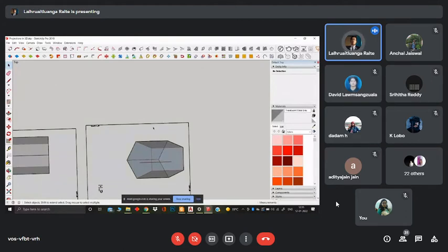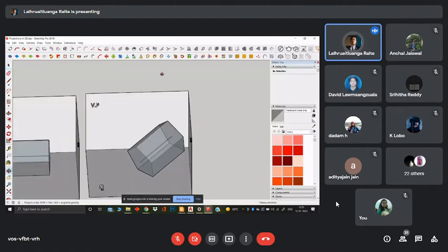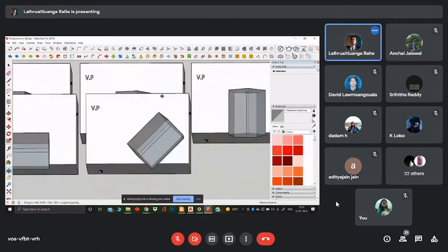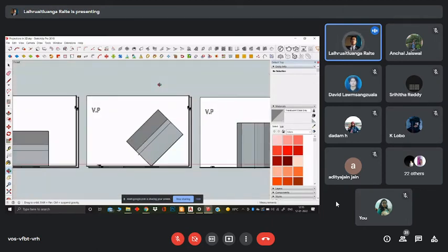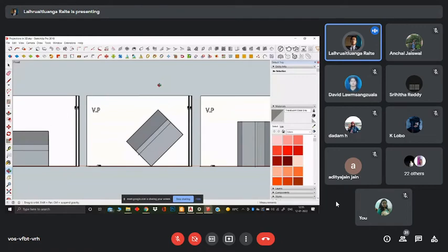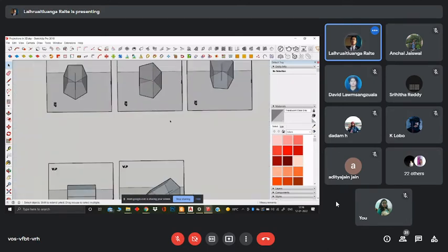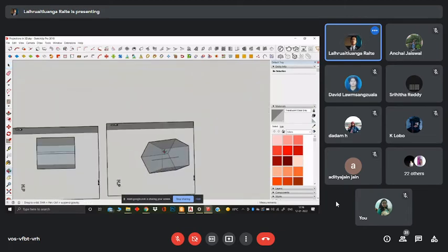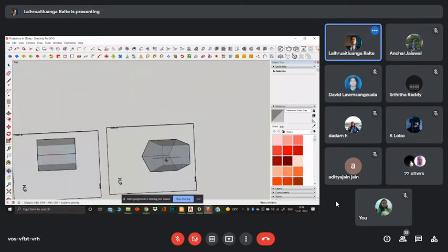This is the vertical plane, or the XY line, and our axis is still parallel to it. So now we have our conditions met: the edge of the base is touching the horizontal plane, the axis is at 45 degrees to the horizontal plane and still parallel to the vertical plane.